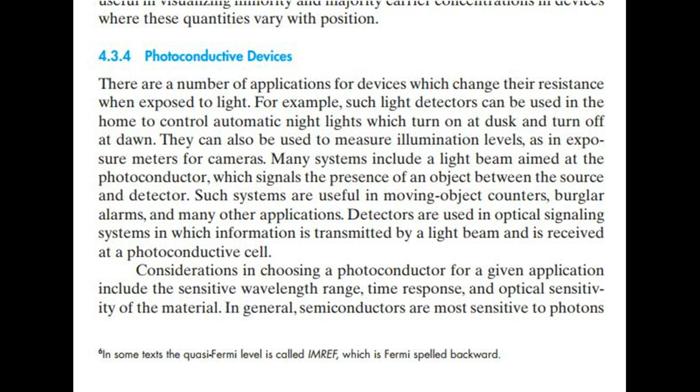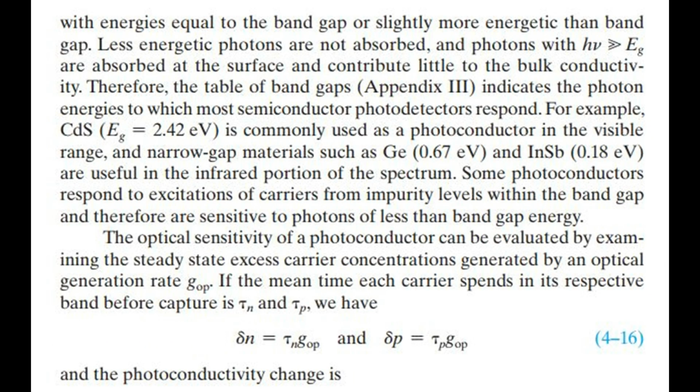In general, semiconductors are most sensitive to photons with energies equal to the band gap or slightly more energetic than the band gap. Less energetic photons are not absorbed, and photons with much higher energy are absorbed at the surface and contribute little to the bulk conductivity. Therefore, the table of band gaps, Appendix 3, indicates the photon energies to which most semiconductor photodetectors respond. For example, cadmium sulfide,